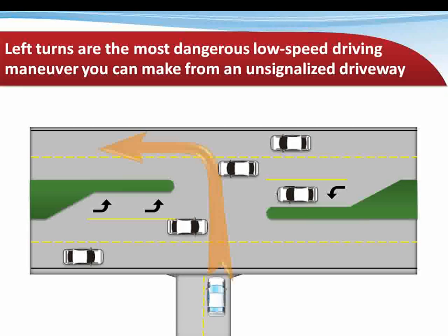Something that you should keep in mind is that the unsignalized left turn out onto an arterial is the most hazardous maneuver you can make. And the reason is right-angle collisions. Right-angle collisions tend to be the most dangerous and lead to the most injuries and deaths on arterial roadways.